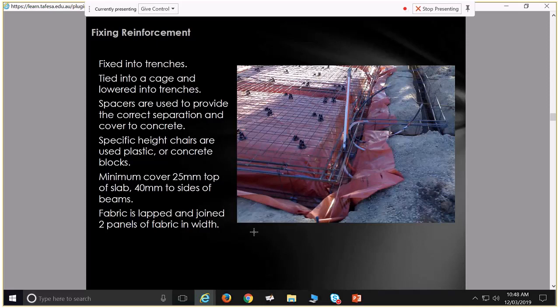So this is exactly what your bars would look like, with all these little lumps on them. And then these are your ligatures, probably 6mm ligatures. Typically you've got 8mm ligatures. The ligature is a thick, strong steel wire that holds all your reinforcing in place. Pass that around to have a look at, and then you've got your tie wire on that.